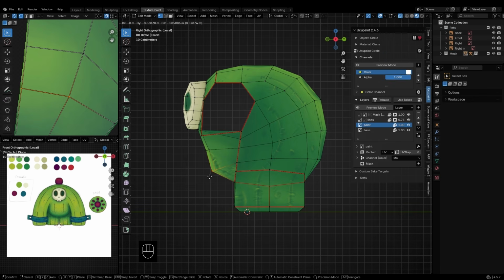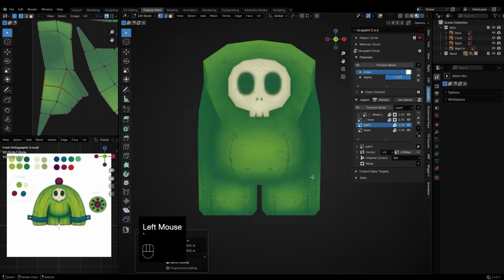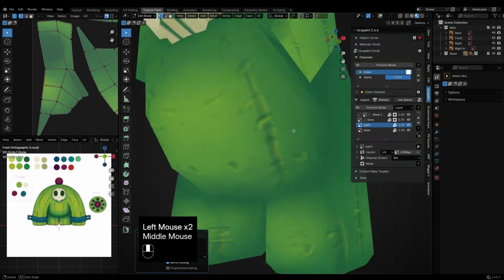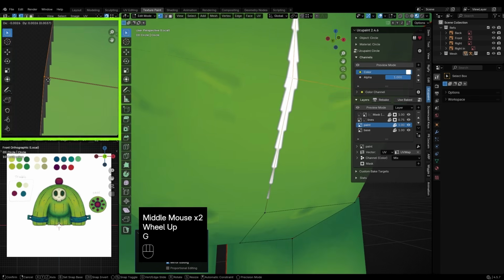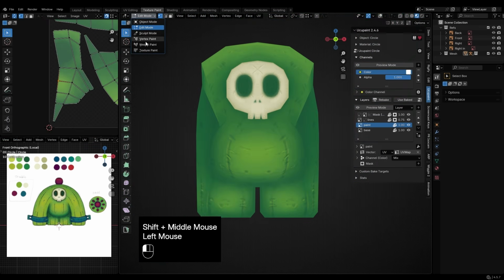After that, adjust the belly vertices until the shape looks better. Make sure to check the center vertices, and make sure the texture still looks correct. If it feels difficult to adjust directly on the mesh, you can also edit it from the UV editor. Then continue adjusting the vertices, and make sure they stay inside the texture borders. Once finished, go back to Texture Paint mode.